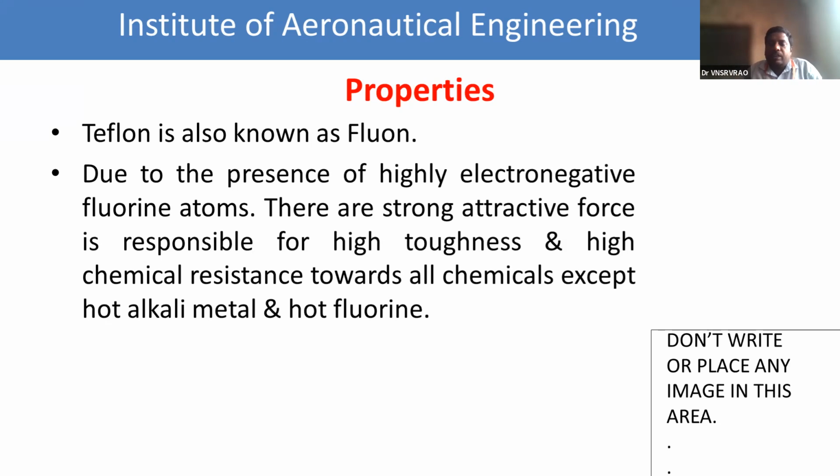This is very, very important. Due to the presence of highly electronegative fluorine atoms, these strong attractive forces are responsible for high toughness and high chemical resistance. That means they are chemically inert towards almost all chemicals except only two situations: hot alkali metal and hot fluorine. So this is about the properties of polytetrafluoroethylene, Teflon.